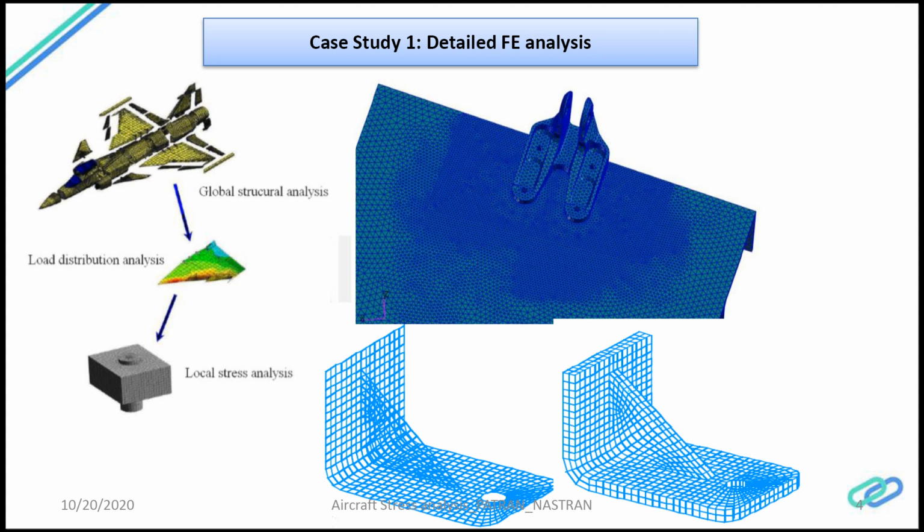And you should have a thorough understanding of the Nastran cards. Sometimes they might ask what the Nastran cards are, and what kind of elements take what kind of loading. Sometimes they will ask what the difference is between RBE2 and RBE3, what your understanding of that is, where you will be using RBE3, and where you will be using RBE2 instead. So these are the typical questions that you could expect in an FE analysis or stress engineer role.